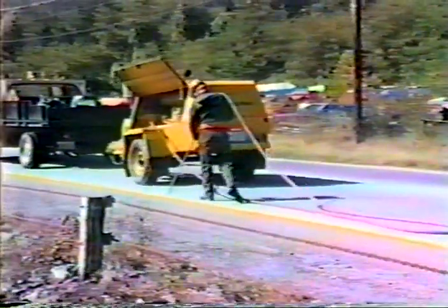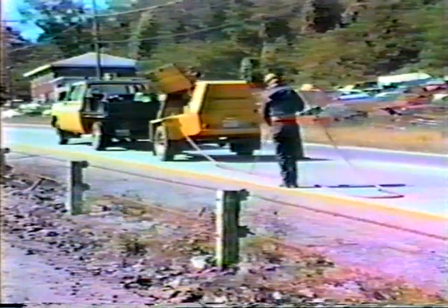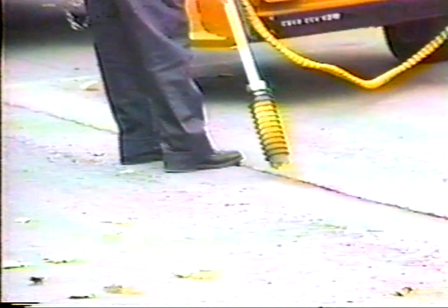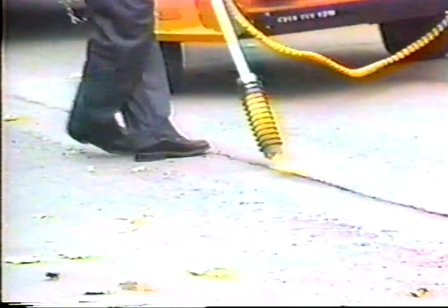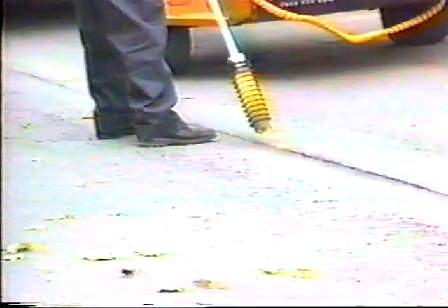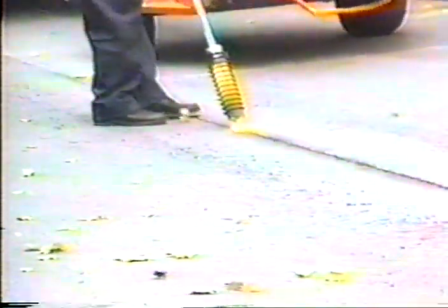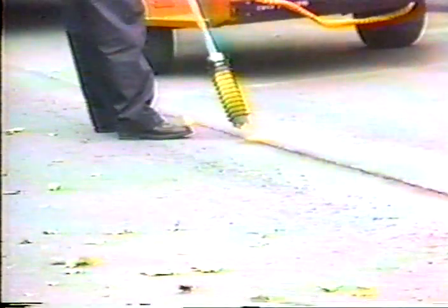Proper preparation is necessary for a successful sealing operation. Sealants will not bond to a dirty, damp, or cold surface. Compressed air is the most effective method of cleaning cracks prior to sealing. Crack sealing should not be done in less than 24 hours after a rain or if there is moisture in the crack. If the pavement temperature is less than 40 degrees Fahrenheit, consider the use of a hot lance. The hot lance is also used for drying damp, not wet cracks. The use of a hot lance will extend the crack sealing season into cooler weather.